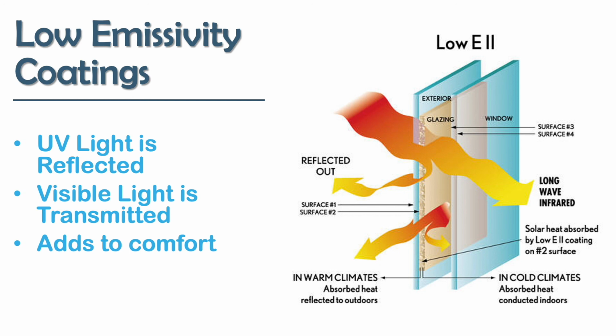Now, the other reason why the low E coating has to be on the inside of all of this is that it's made from microscopically thin layers of silver. And if they get wet, if they're exposed to moisture, they will tarnish and be less effective, and also create that sort of speckly look that you might have seen in some older double paned windows. Also, we're protecting it from scratches, which would keep it from being as effective.